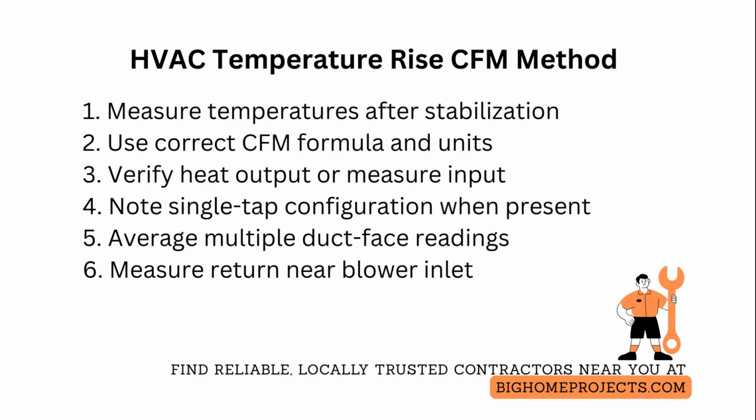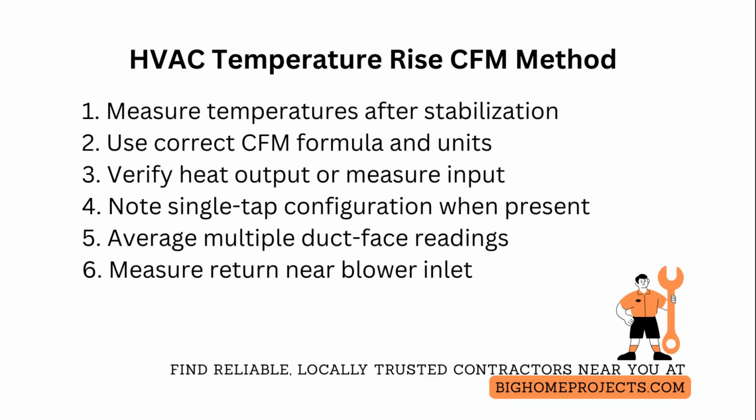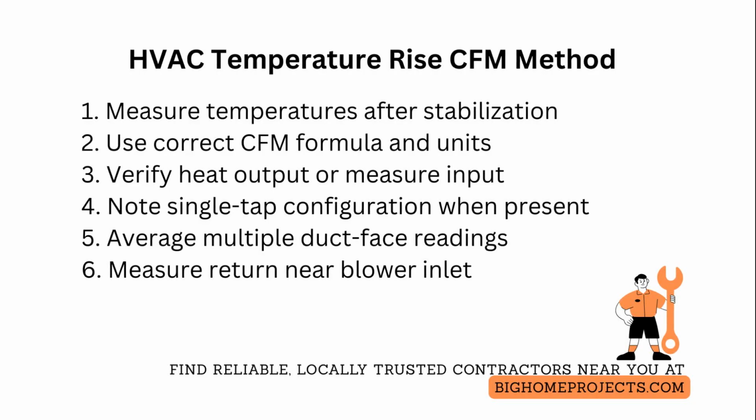For long runs, account for heat gain or loss in the duct by measuring temperature at the coil and at the supply register and note duct insulation R value. If significant, place probes at both ends and use the coil side delta T for CFM calculation.